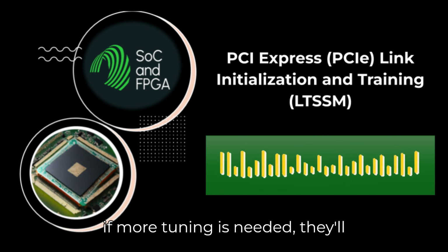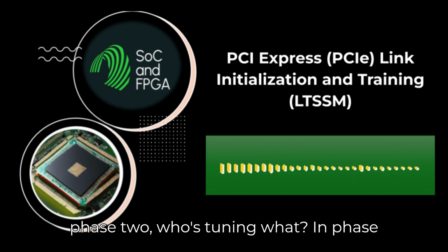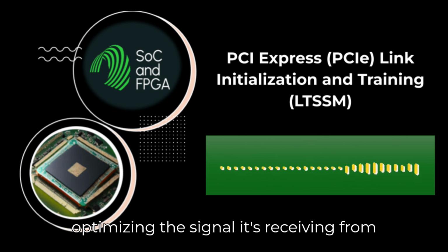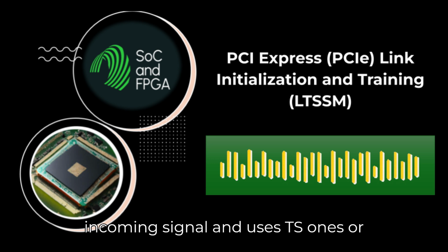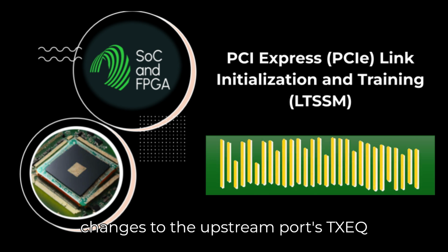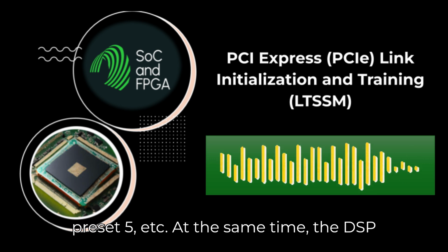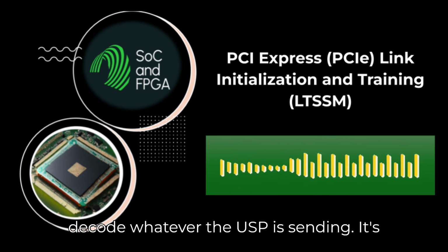If more tuning is needed, they'll indicate in the TS1s that they intend to proceed to phases 2 and 3. Okay, phase 2, who's tuning what? In phase 2, the downstream port takes charge of optimizing the signal it's receiving from the upstream port. The DSP analyzes the incoming signal and uses TS1s, or special EQ TS2s, to request specific changes to the upstream port's TXEQ settings: try this coefficient, use preset 5, etc. At the same time, the DSP is also tuning its own RxEQ to best decode whatever the USP is sending.